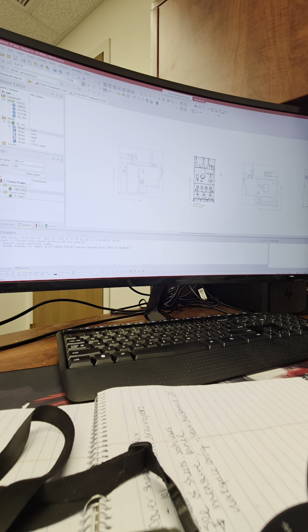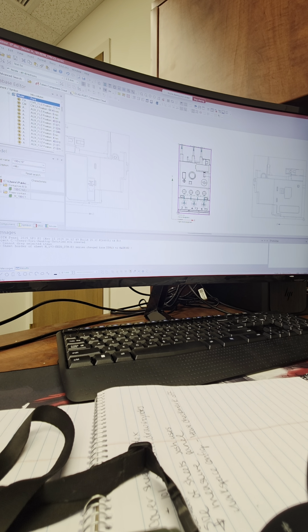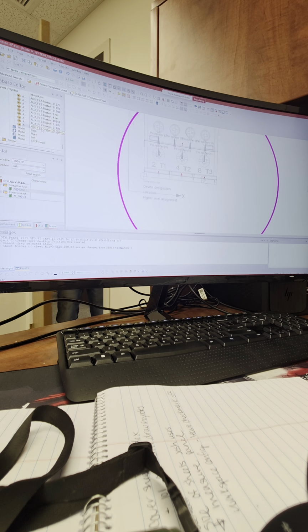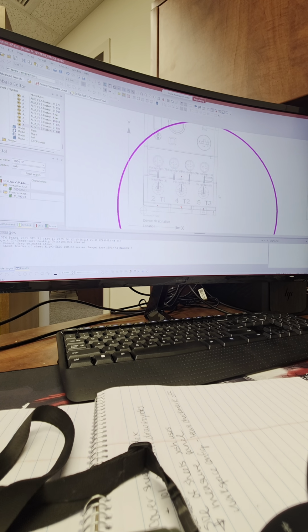Your front view at the moment also has a little plus next to it, which means there are other objects that somebody at some point added to the front. So if you expand that, you see all these different slot points. Again, I see that there are just way too many of them for this to be even a real thing. So if you start from the bottom up, just so we can find out what these items actually are, double click on any of these, or just make the field slightly wider so we can see all of these full names.